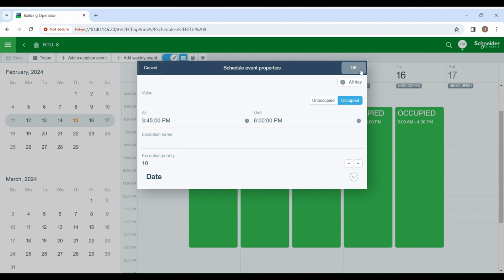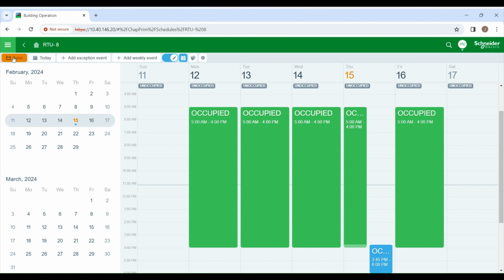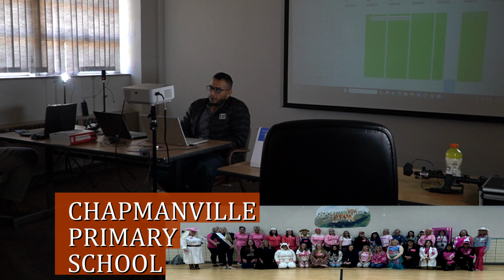You may have already said it, but do these have an optimal start where they'll be at temperature, whatever you schedule, or do you have to plan for some warm up, cool down time? Well, the optimal start, from what I saw, is based on my unoccupied set point. We put the unoccupied set point at 78. So if we exceed the 78, the units will run.